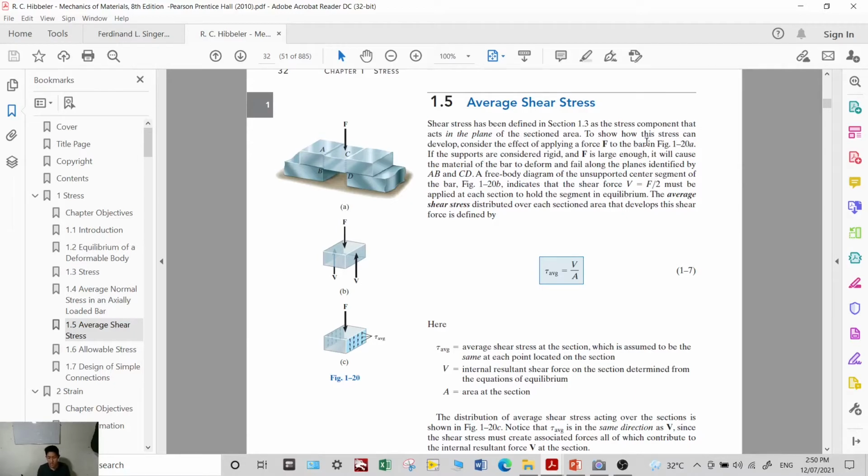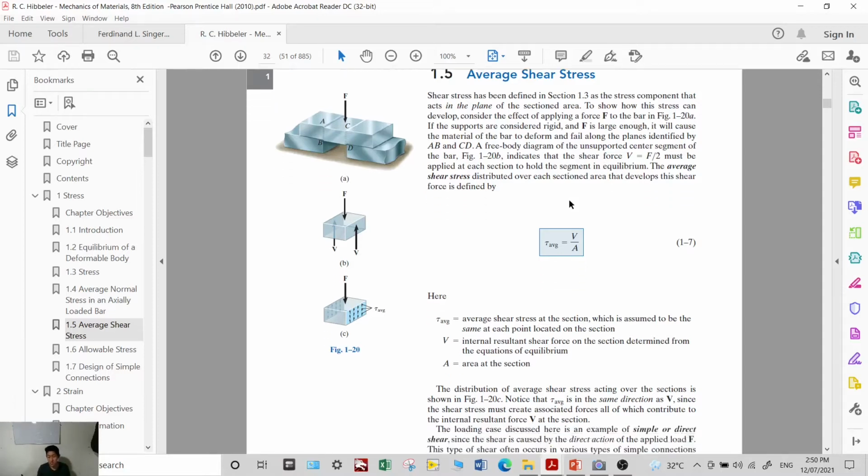Again, shear stress acts in the plane where your force is parallel to your area. For example, in this setup, you have blocks B and D, and on top of them is block A. When you push it, the stressed areas are these two. The force is parallel to that area, so this is shear stress.